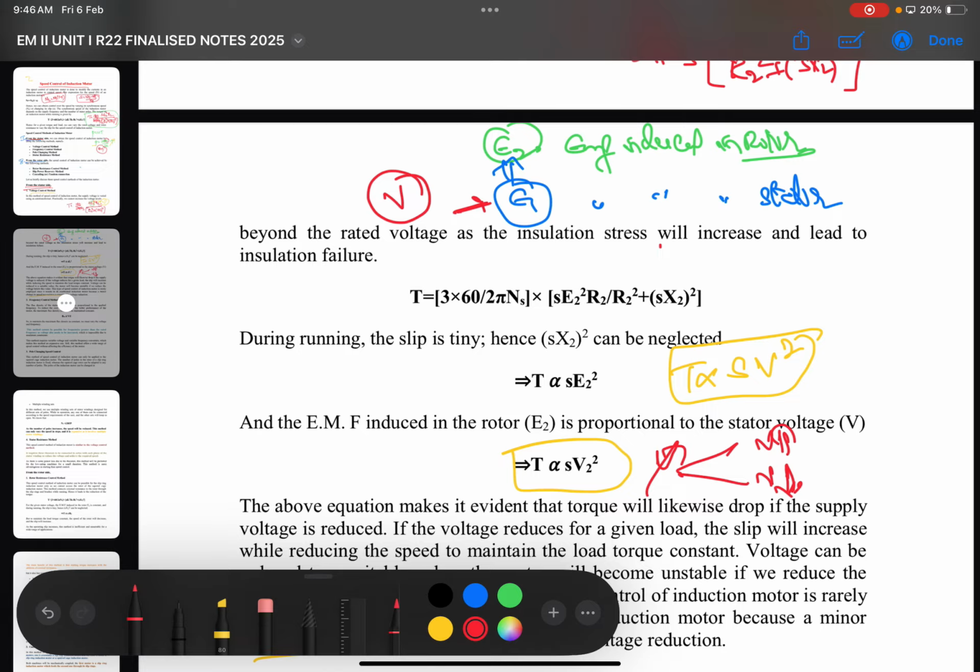No, it won't change here. It is by default a fixed value, which is 260. Already the voltage is 300 volts and the insulation strength is 260. So automatically insulation failure will take place, and once we touch that, we can experience the shock. This is how we get an electric shock. So if the supply voltage is more and the insulation strength is less, then the insulation breakdown will take place, and because of that we can experience a shock.